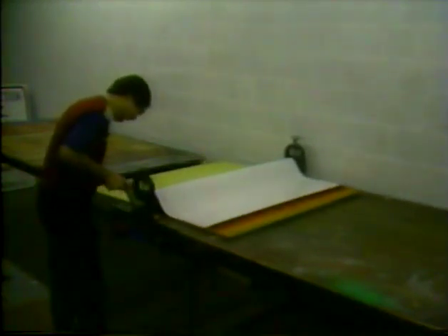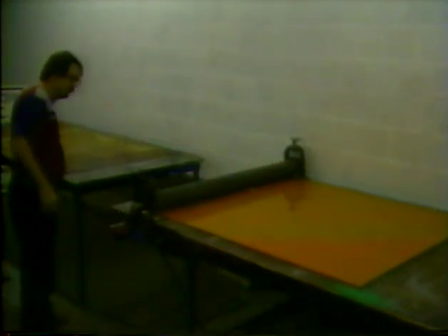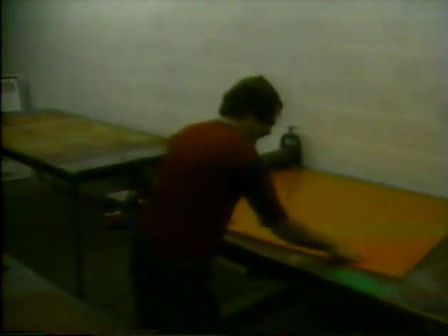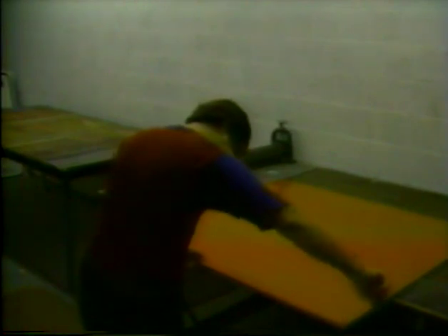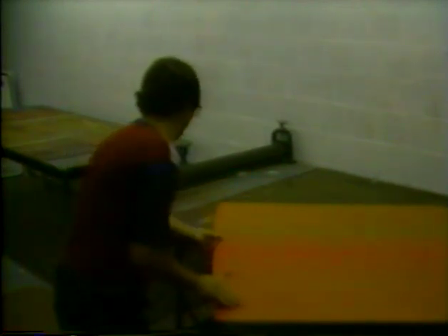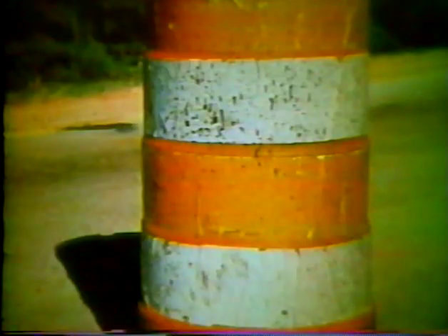All signs and channelizing devices that will be left on the road at night must use an approved grade of reflective sheeting to provide sufficient nighttime visibility. The condition of the sheeting largely determines the effectiveness of the device. Sheeting that is torn, peeling, cracked, or splattered with asphalt or concrete will not perform well under the best conditions, but it's particularly bad at night.